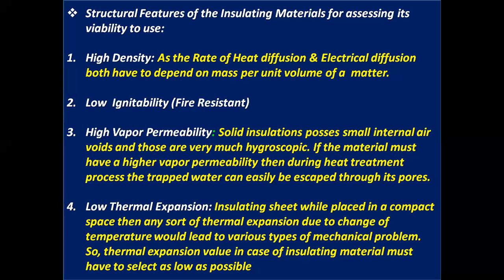Low thermal expansion. Insulating sheet, while placed in a compact space, then any sort of thermal expansion due to change of temperature would lead to various types of mechanical problem. So, thermal expansion value in case of insulating material must be selected as low as possible.